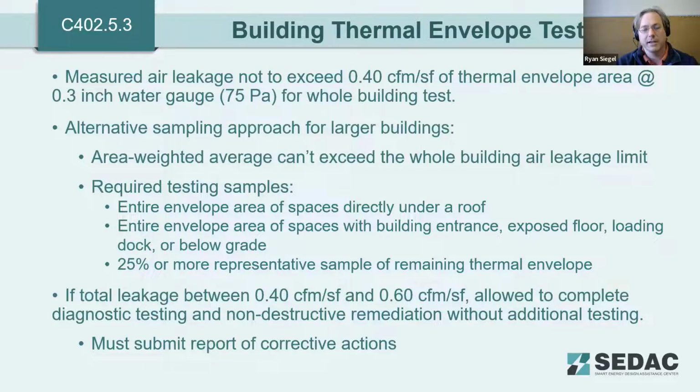And the biggest thing is to make sure that the entire area that's directly under a roof is tested. Any area and spaces that have building entrances or exposed floor underneath. So if you have parking underneath, that bottom floor is going to need to be done as well, or any loading docks or below grade. And then a 25% or more sampling of anything remaining beyond that. So